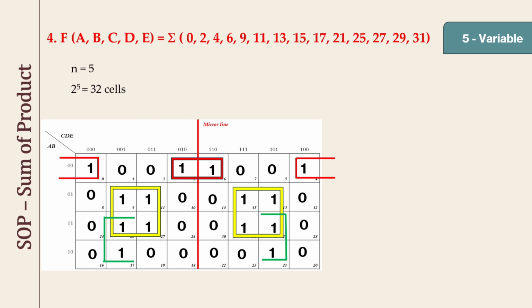Now let's move on to naming these groups. Let us consider the first group. In the first group, B is common between the second and third row. And when you go for columns, we need to compare the second, third, sixth and seventh columns. In between these 4 columns, we can see E as common. So we can name the group as BE.